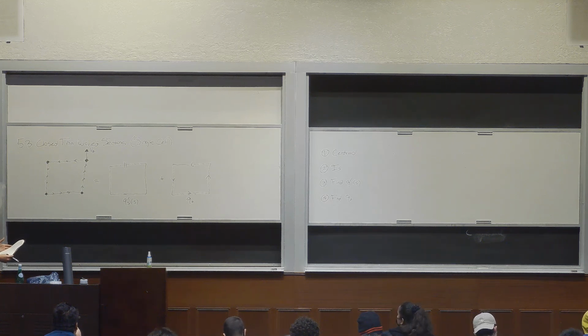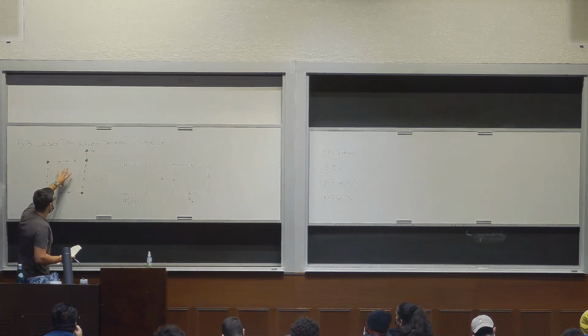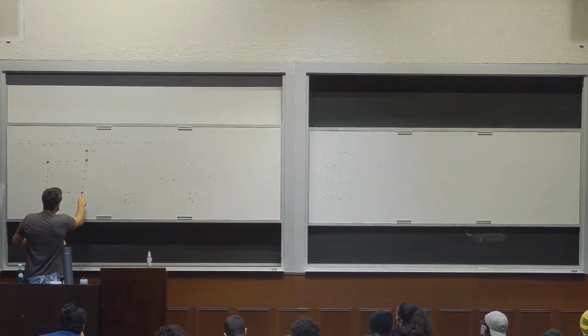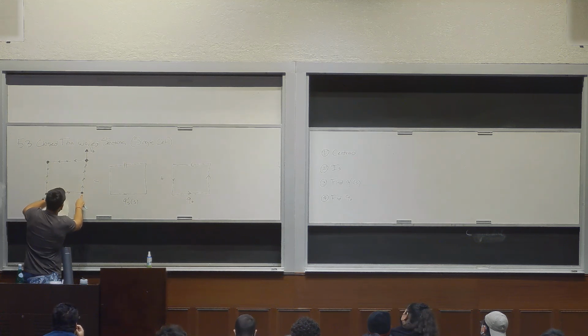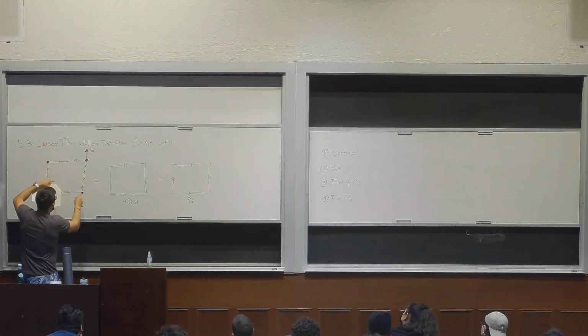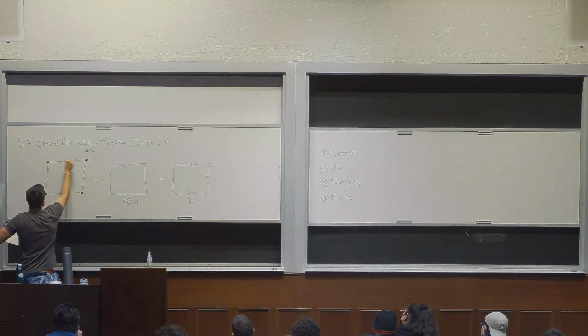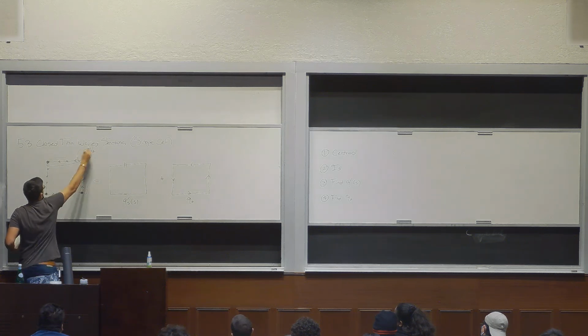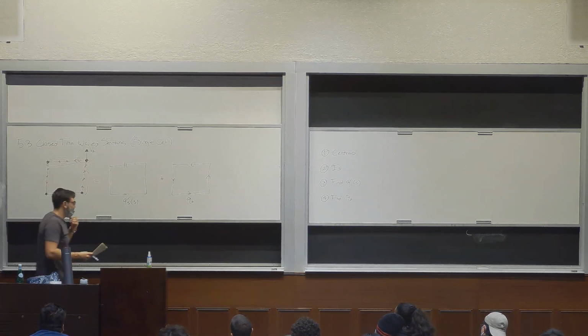What you have to realize is that these shear flows will generate a torque about any given axis. If I choose, for example, this point to take the axis about where the things are twisting, you can choose any given location, but let's say we choose this point. Then this shear flow won't produce a torque. This one won't, this one won't either. This one will produce a torque. And that torque, so this force times this distance, has to be equal to the torque generated by that. That might be a little confusing. Hopefully it makes sense in a bit.